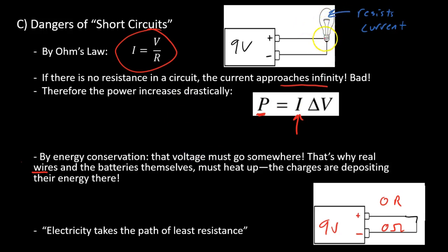All right, a short circuit refers to when you have something like this going on, where you are missing out on resistors. Maybe you design a circuit that looks like this, but by accident, there's actually a wire going like this. And so you're taking a shorter path. You're not going through resistors. That can really mess up your circuit if you wanted to have a very specific amount of current, and now all of a sudden you have much more current than before.